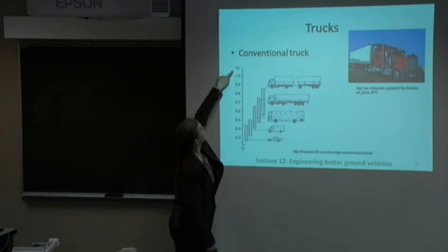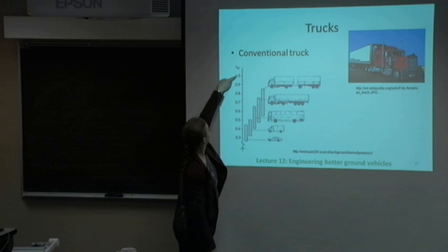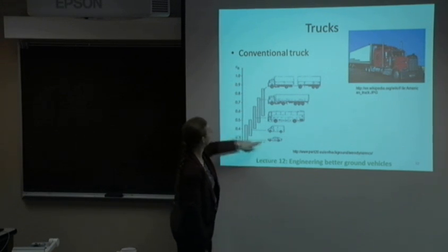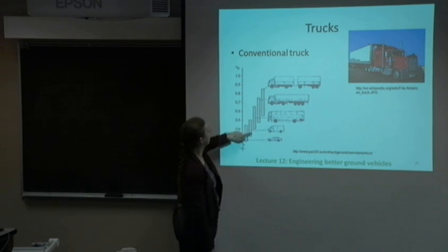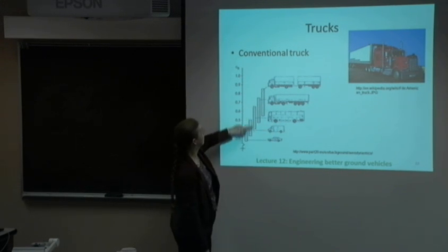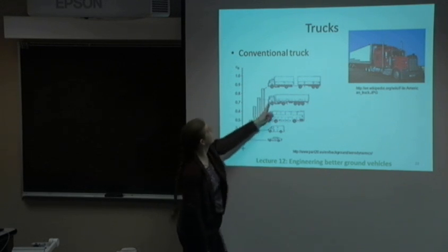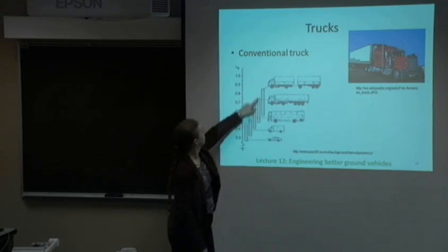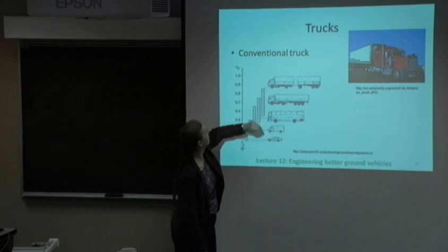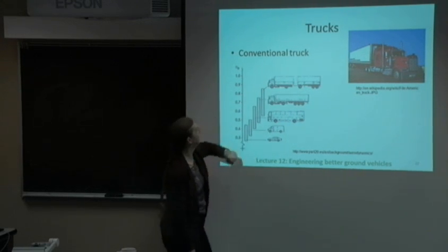This is drag coefficient here, and this starts at 0.3. So cars are down here, 0.3 to 0.45. A van, a little bit higher. A bus, a little bit higher than that. A standard truck like this. Notice this one's long. It has a range, and then this double tandem. So you're going to have problems with this gap.